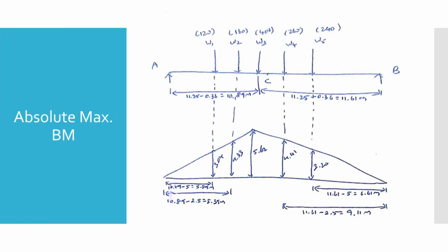The standard structural criterion dictates that this maximum moment occurs directly under the heavy load closest to the resultant, when the beam's centerline perfectly bisects the distance between that specific load and the total resultant force. In this problem, our closest heavy load is W3. The distance separating wheel load W3 and the resultant force R is exactly 0.72 meters.